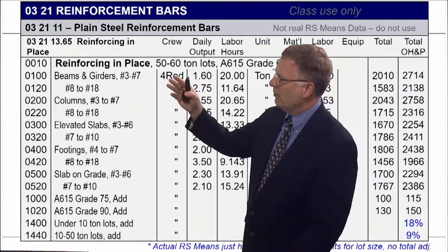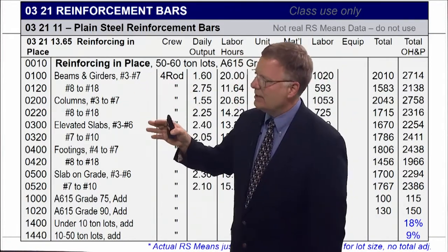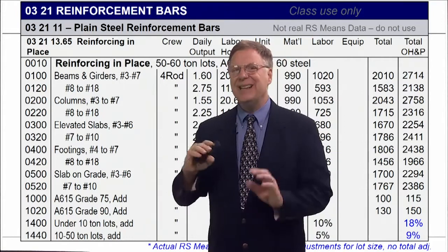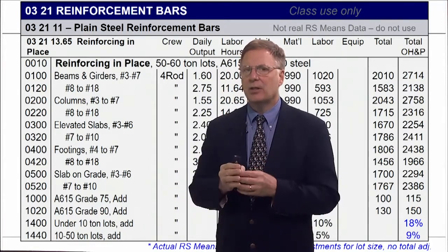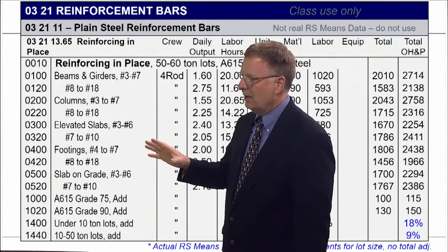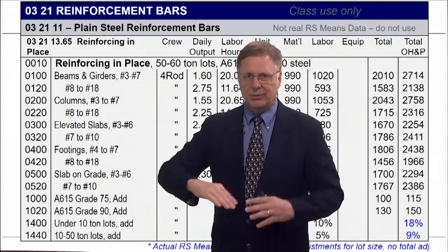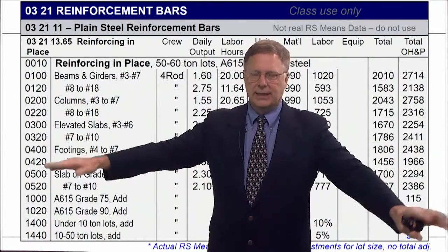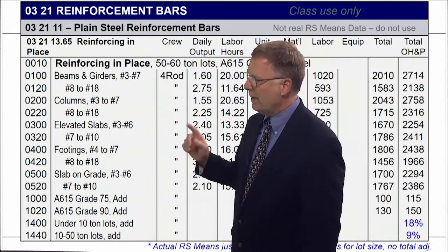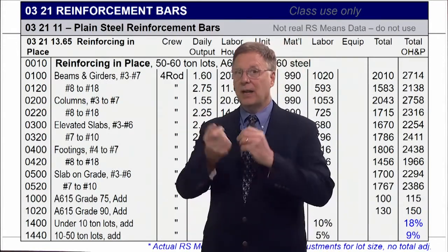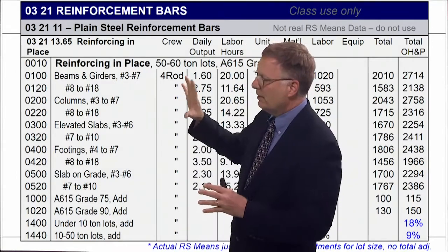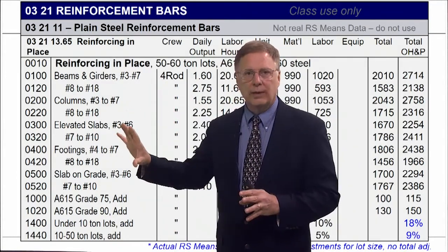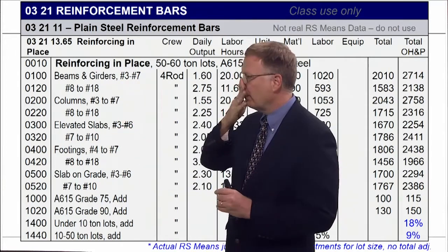So we're looking down here and we find out the reinforcement is sized or priced based upon the application. And that kind of makes sense because if we're doing a slab, that is completely different. I mean, we just have long rebars kind of laying there. Same thing with footings. Compared to a column and a beam where you might even have spirals going in a column or a beam. So you've got to figure out what you're doing with these things before you actually start pricing them out.